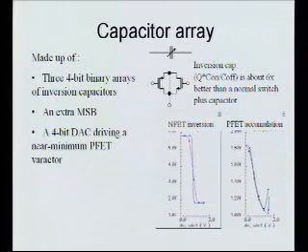The other thing you might be able to get is better Q. With the switchable caps, you can usually get pretty good Qs of 40 plus. The varactors are in the same range. So if you can beat 40 for your Q, then it makes sense to use something like a MEMS cap. But I don't think it's absolutely clear that you need them. That's an area of research, if you can make them good enough to be worth it.